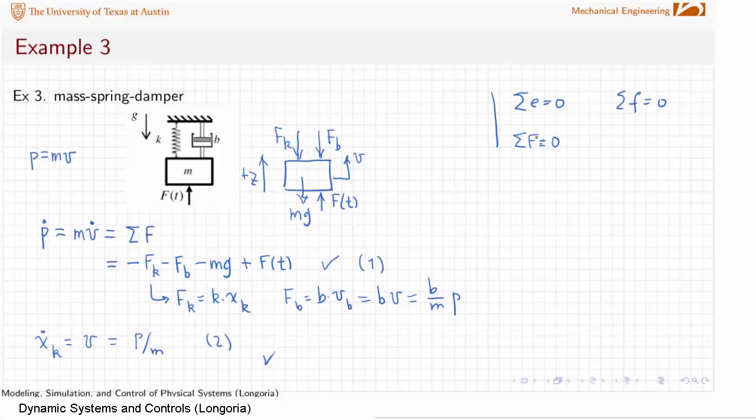But what you have to think about is that equation is basically the Newton's law equation, except that this equation has that P dot term in there. The P dot is, remember, an inertial force, so you can think of that being within that relationship. In this case, the sum of the forces, the sum of the flows, the sum of the velocities equals 0 does not apply here because there's only one velocity. So this is really more applicable when you have multiple velocities in a system where you have some kind of kinematic compatibility. But in this case, this general relation relates to the Newton's law relation.